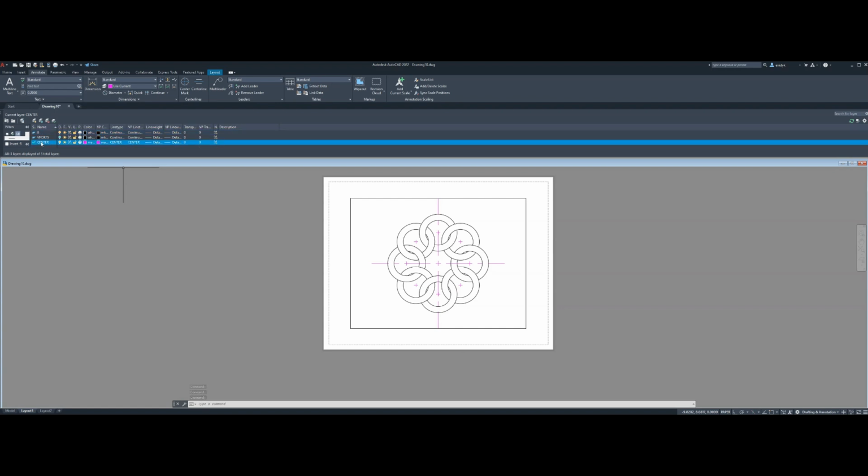I will go back to my center line layer, and I will use the change properties command again to change the viewport layer, which was on the default layer of 0, to the viewports layer, which is turned off. So CHPROP, enter, select the viewport, enter LA for layer. The new layer name is viewports. Double enter, and that box disappeared.